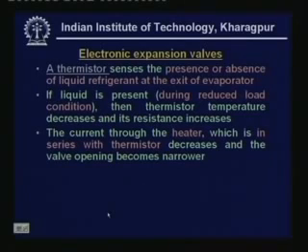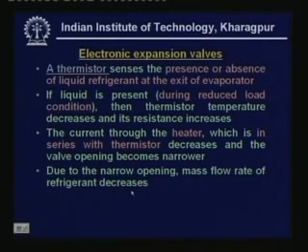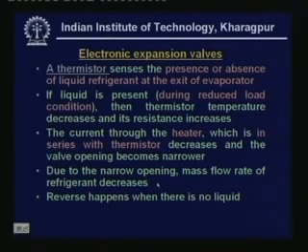So as I said, the current through the heater which is in series with the thermistor decreases when liquid is present, and the valve opening becomes narrower. I am sorry, when the load decreases, the valve becomes narrower, and due to the narrow opening, the mass flow rate of refrigerant decreases. And the reverse happens when there is no liquid.